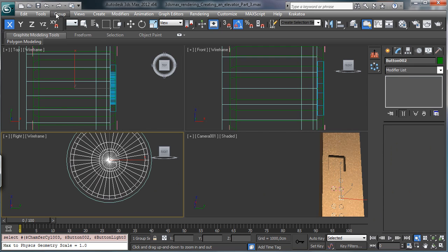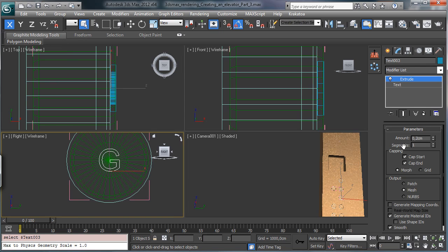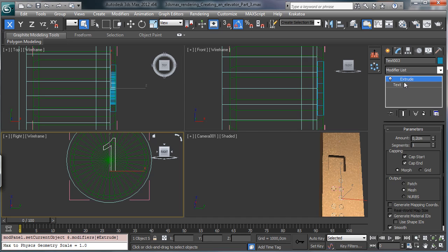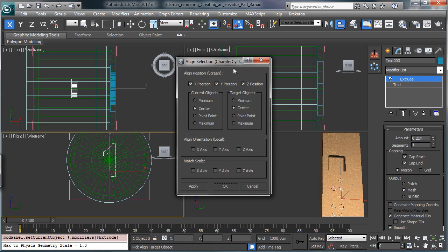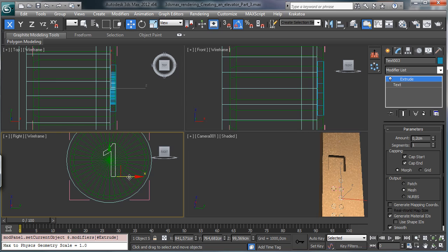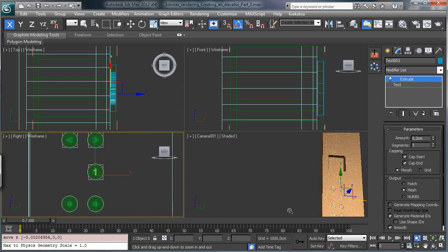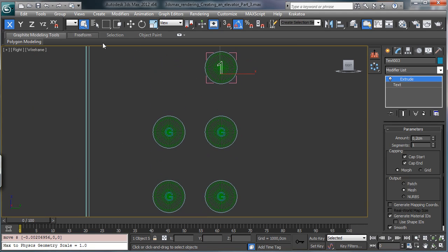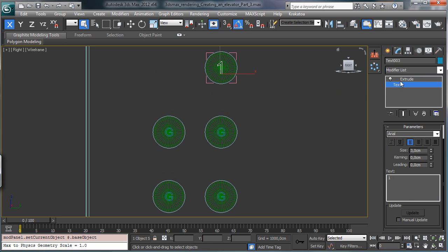Okay, let's go there, and now we have to work with this one. Let's zoom, group, open, select this one, and this will be 1. And let's say that we start to have maybe 3 centimeters. Okay, and we can choose to have it over the x-axis, the y-axis, and not the z. Perfect. So we have the 1, and we used 3 centimeters.